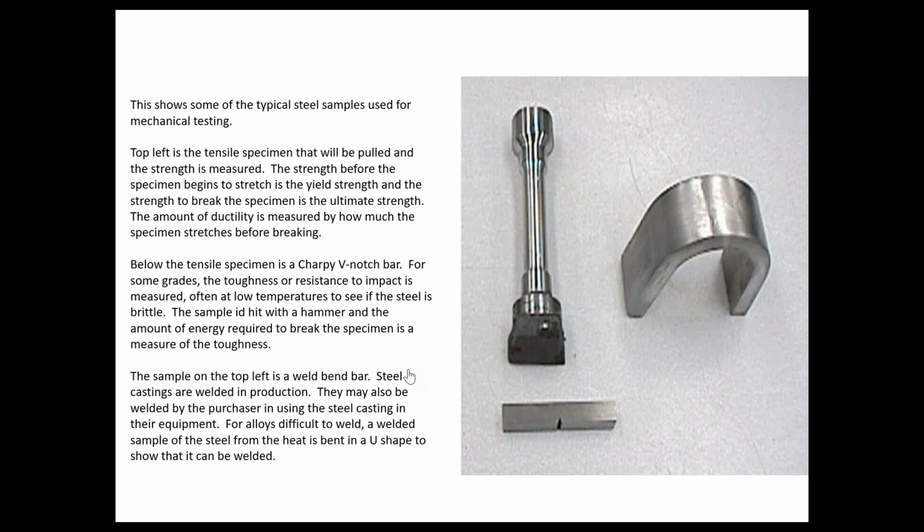One of the challenges we face is because people have the experience with cast iron breaking, being brittle, many people think that any cast material is brittle. But the steel that we cast is the same kind of steel that they roll into bars and plates. And because we make to the same kinds of specification, ASTM specifications, we test every heat. So we do tensile tests, we do welder qualification, we even do toughness testing. And so the steel that we make is just as much steel as any other product.